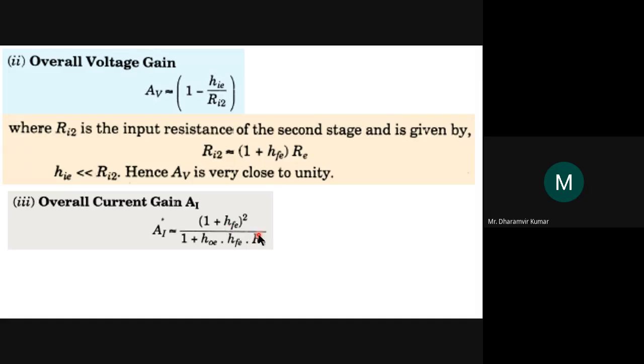And we know from the diagram that the output is taken across the emitter branch, and the input is fed from the base branch. So output is the emitter current and input is the base current, and emitter current is generally very high as compared to base current. We know that thing, so the current gain has to be high. So can we justify that thing here?